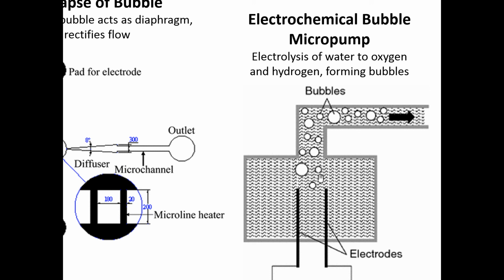In microscale devices, density effects tend to play a smaller role. So sometimes the Laplace pressures and the affinity of the droplets to the walls of the channel make it difficult for the bubbles to just go up vertically. But it'll still work. So one way to expel the bubbles from the chambers is, you can use the density effects to do that, like you're suggesting. Okay. Good point.